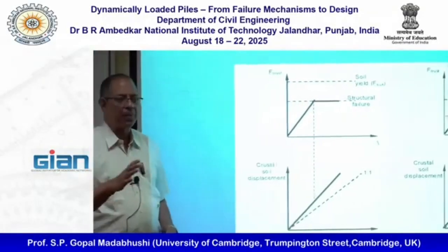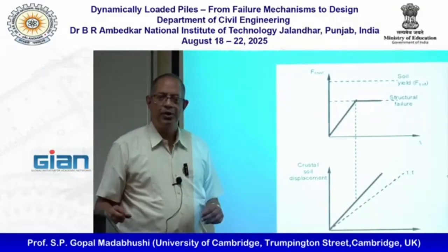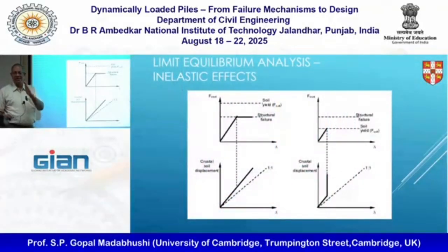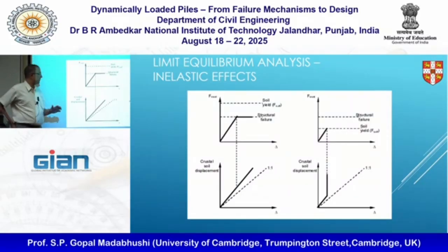So in elastoplastic analysis like this, you simplify the whole problem by saying, well, I got the elastic bit and I got the plastic bit. You do not take the increase from first yield to peak and then softening. For steel piles, that can happen. But you ignore that bit and say, that is the factor of safety in my back pocket. So that is normal plasticity assumption.